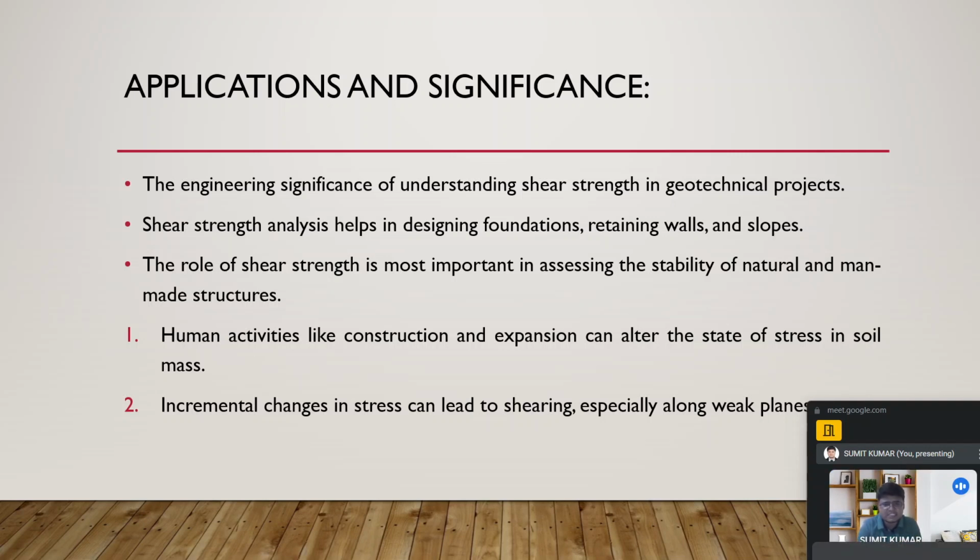The role of shear strength is most important in assessing the stability of natural and man-made structures. This needs to be understood by you, because if we are studying any natural structure, we need to know the value of shear strength, so that we can sustain this much load after applying the factor of safety.